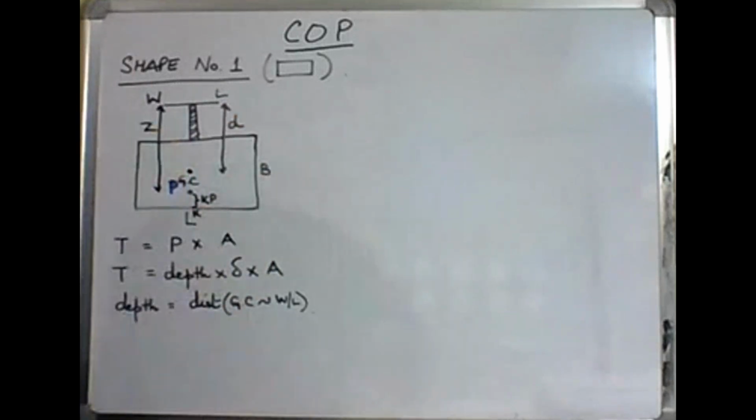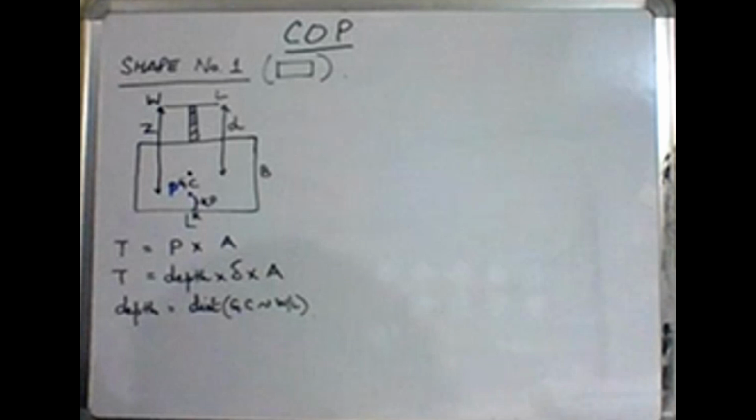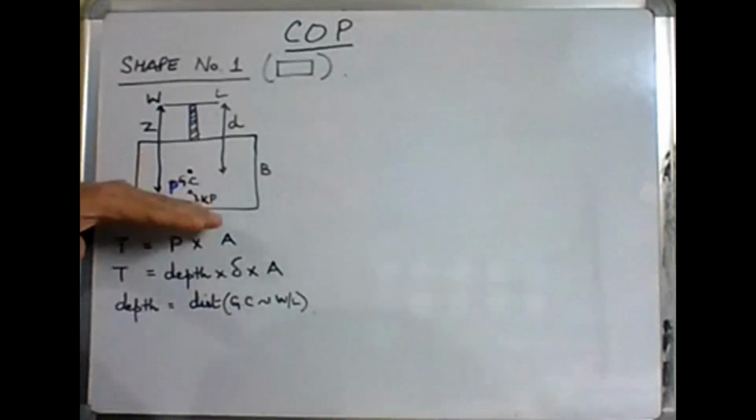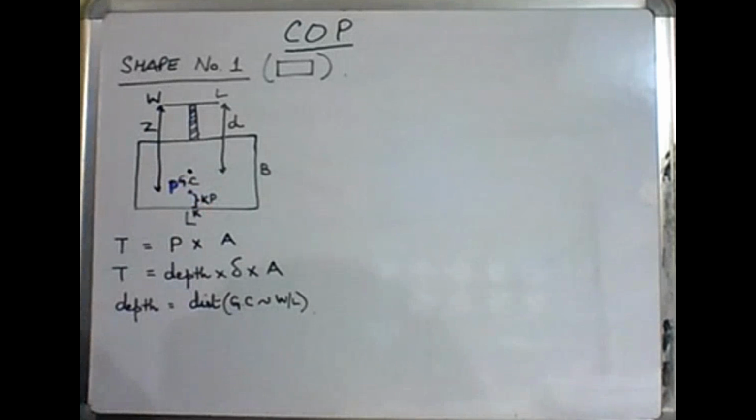But एक point P है जहां से वो bulkhead give way करेगा, वो point P GC के नीचे है. So therefore, that point P is assumed to be the point at which the entire thrust is acting, also called as center of pressure, and that is at a distance Z from the water line.